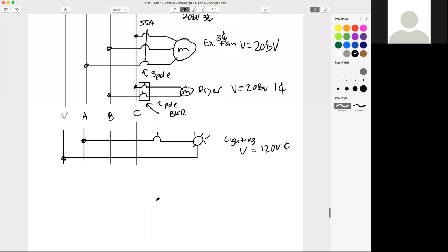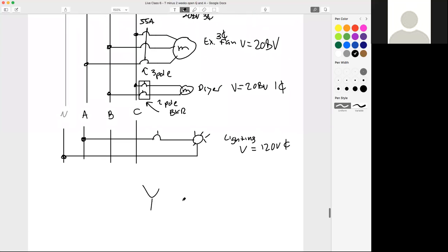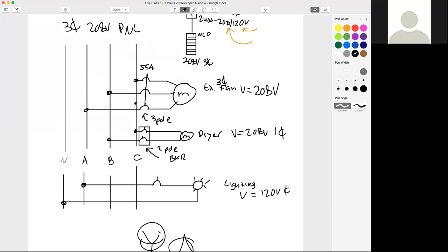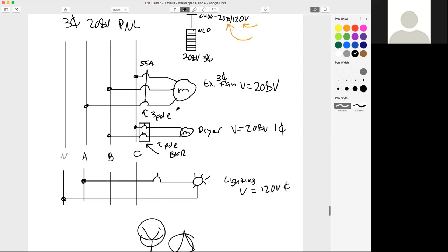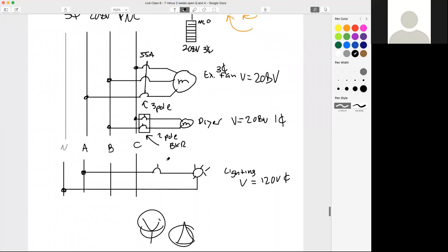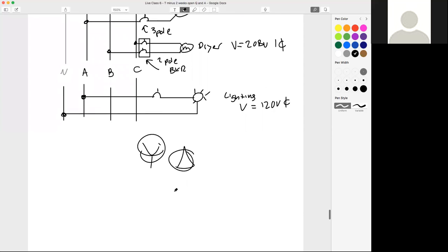We're so used to thinking in terms of delta, Y, and stuff like that we forget what the point of all this is. We're trying to feed power to a panel or a motor control center or something like that, right? And when we're in that panel, we just have bus bar we're connected to. And really, delta Y doesn't matter, right? Delta Y is just the winding configuration. If our panel is Y fed or delta fed, the only difference is that we're going to have a neutral, so this will have to be a Y fed.